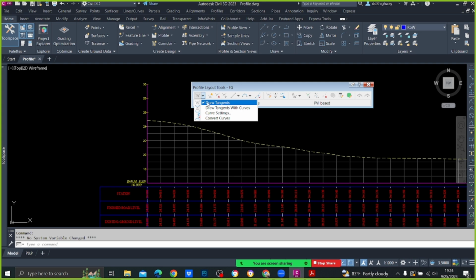So on top of the existing ground, that is 100 millimeter. So what I'll do is match my design profile to the existing profile, and then I will elevate it with 100 millimeters. Okay, so you will understand what I am doing when I have done it.